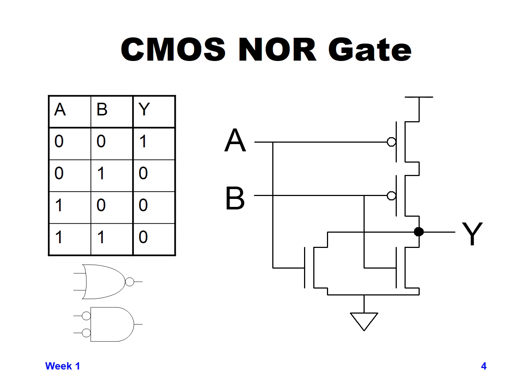the output. Now, in all of the other three cases, where either of the inputs, so if input A is a 1, or if input B is a 1, in either case, we are going to have one of the PMOS transistors turned off. So we will have no path up to VCC, and in either of those cases where one of A or B is on, one or both of the NMOS devices will be turned on, and so we will have a path to ground or 0.